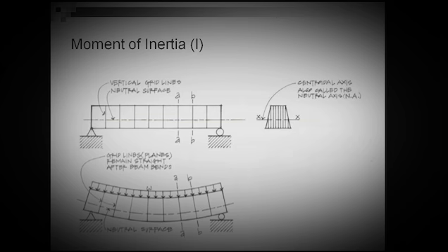The second moment of an area is used for the moment of inertia. If there is a third or fourth or fifth, those are not yet used in our structural analysis. They may have different applications, but definitely not in our regular beam flexural analysis. So for structural design, we only go up to the second moment of an area.